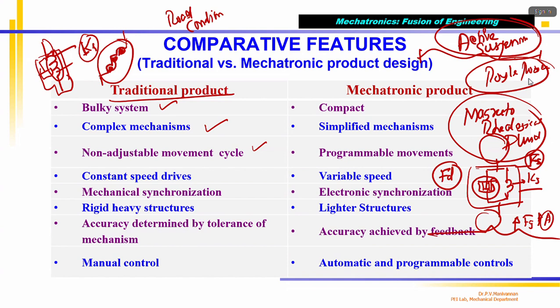Correct? In active suspension, there will be a spring and a damper. In the damper, instead of regular oil, viscous oil filling, they fill with what you call magnetorheological fluid. Correct? Any fluid has a viscosity. The viscosity of any fluid is fixed. You cannot change it, though it varies a little bit if the temperature of the fluid is changed. But viscosity for a given fluid is fixed. But with magnetorheological fluid, by applying an external magnetic field, you can increase or decrease the viscosity.